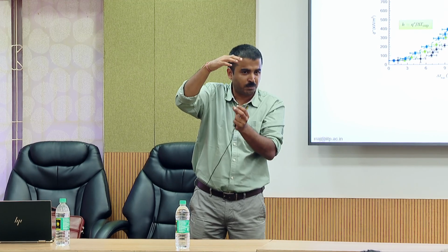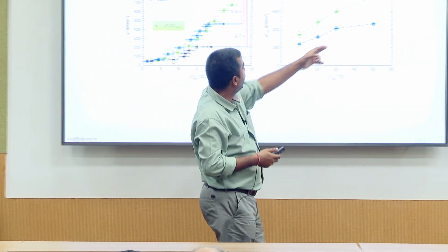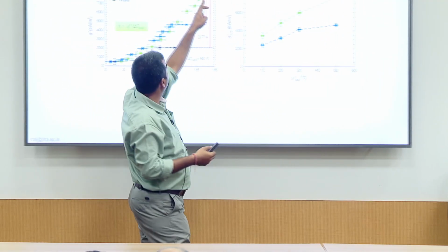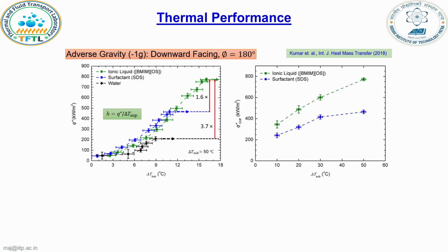You have to, once departed, somehow get rid of that bubble, right? And that's why initially, in the boiling experiments you have seen, we have a subcooling of 50 degrees, and we get these critical heat flux values, the values here. As you start decreasing the subcooling, essentially the trend is showing you will go to 0, which makes sense. Yes, you can have a bubble departure event, but eventually you need to have a sink for that bubble. Otherwise, once departed, it's going to traverse back up.